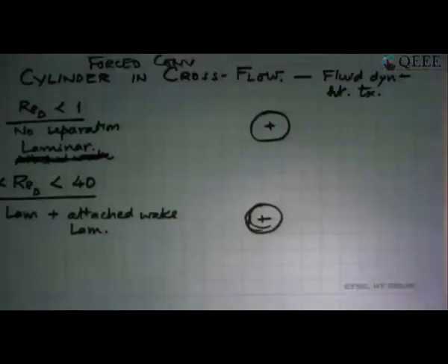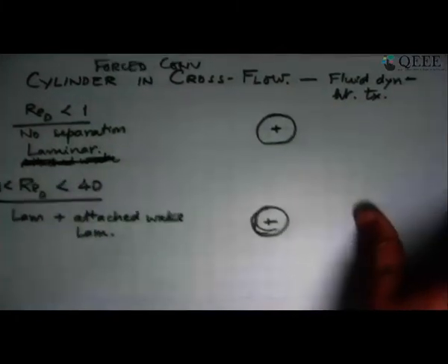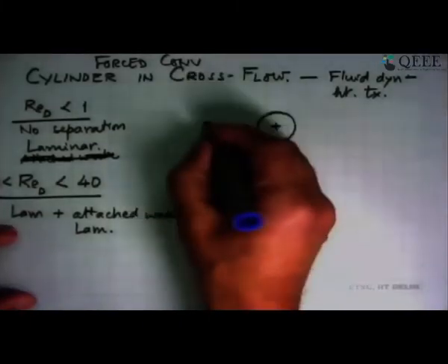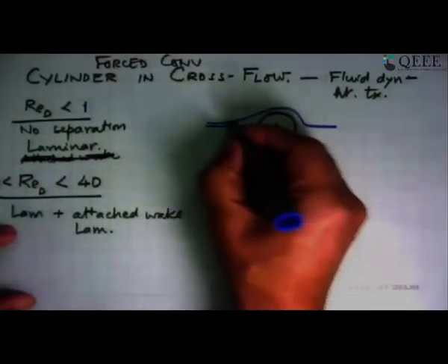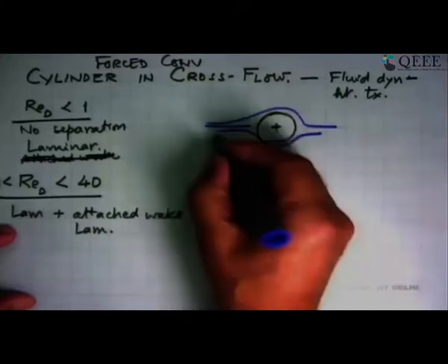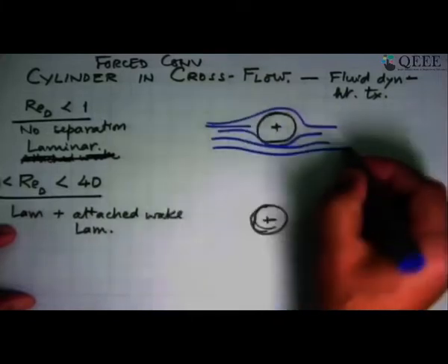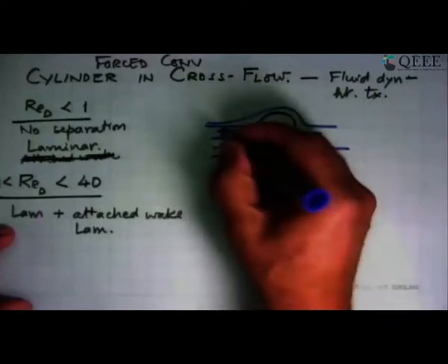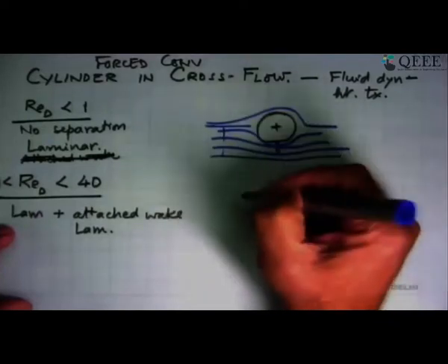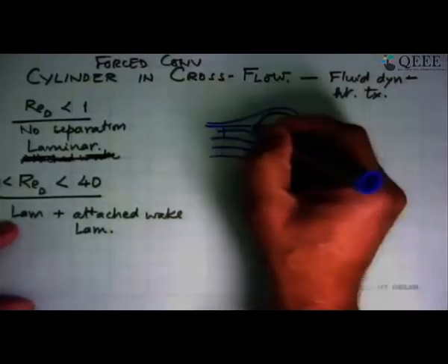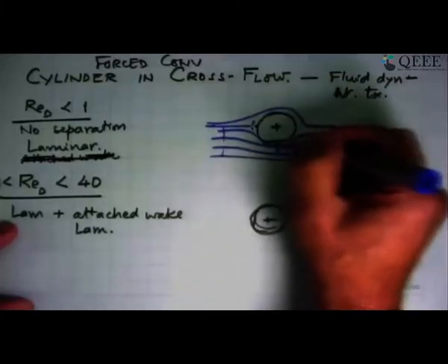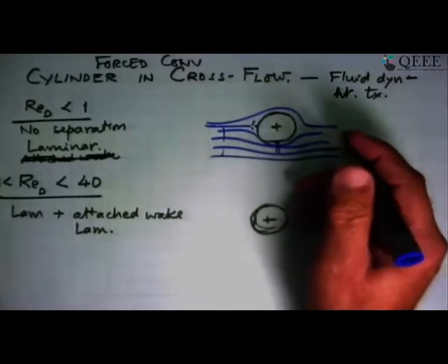The first one we have is that first picture that we saw, where the flow was completely symmetric and attached. So it went off like that and joined up there. From the bottom it went up there, it went up there, and it went up there. These streamlines here were squeezed in compared to this. So the heat transfer coefficient here is going to be better. Here it's going to be something, and then at the back it will recover and be almost symmetric, but it will not be uniform all over the place.